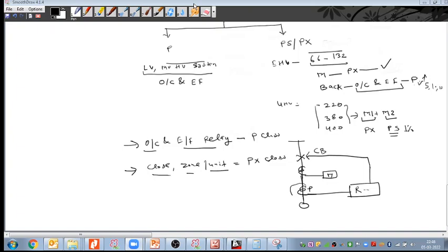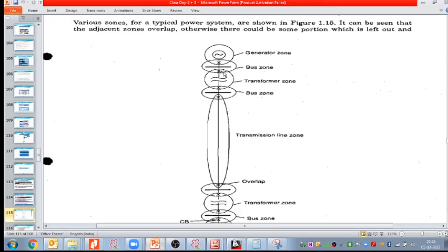Yes, correct, Raghunath. Your statement is perfect. Protection whose boundary can be defined is a unit protection, and if the boundary cannot be defined, it is non-unit protection. That is why overcurrent is a non-unit protection, because we do not define any boundary. In unit protection we define the boundary, and as we discussed here, we are defining the boundary of the protection. It means if any fault occurs beyond that boundary, that zone's relay should not operate. Due to that we get reliability, and we can easily find the fault in the grid. That is the advantage.